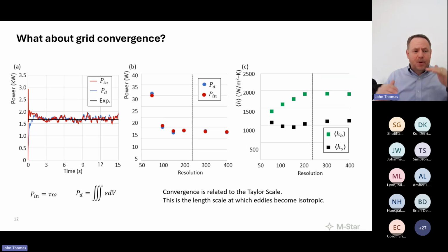Said again, if you're not bookkeeping energy dissipation, you're not going to be able to reliably use an EDR-dependent relationship to predict convective heat transfer. And so foundationally across the board, we can do a good job of matching power in equals power out. And happily, power in agrees with measured power number data, corroborating that the simulation is having a good handshake.